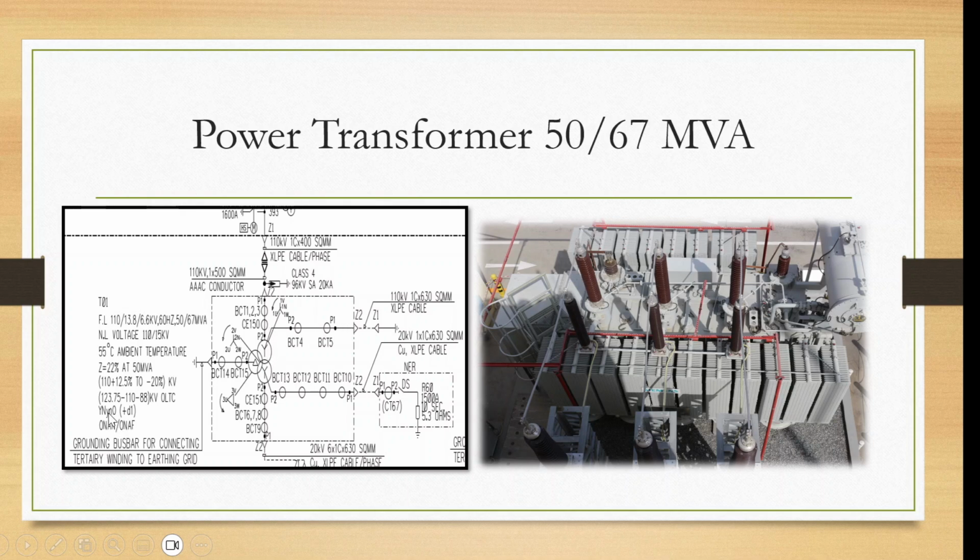And this is the primary side. The secondary side is yn, in small letters. This is small yn, and this is the neutral. And 0 means both voltages will remain in phase with 0 displacement. So this is the vector group YNyn0 for the primary and secondary.